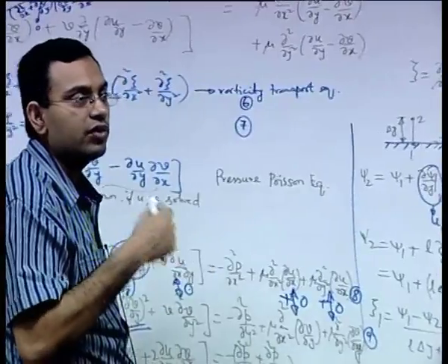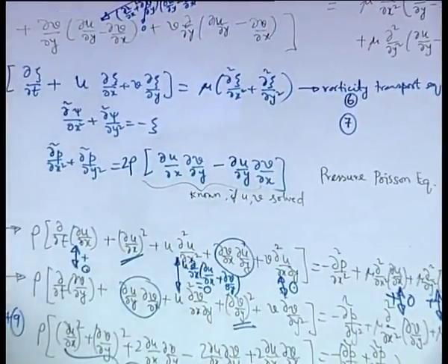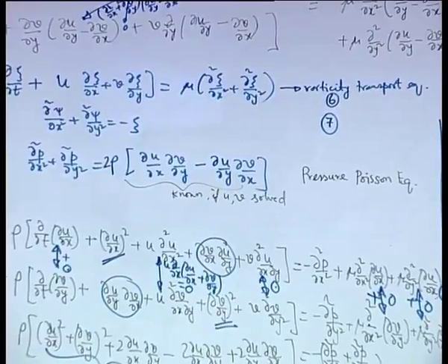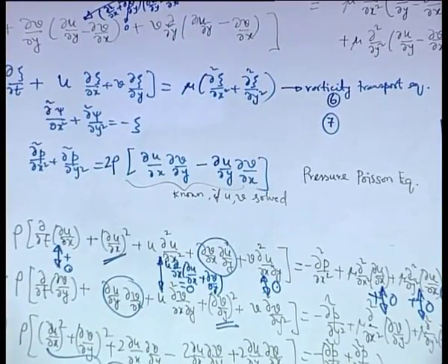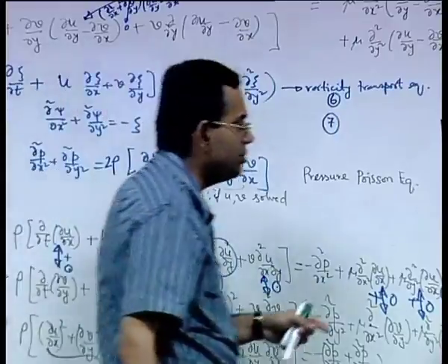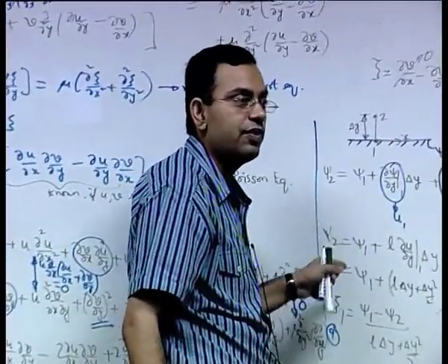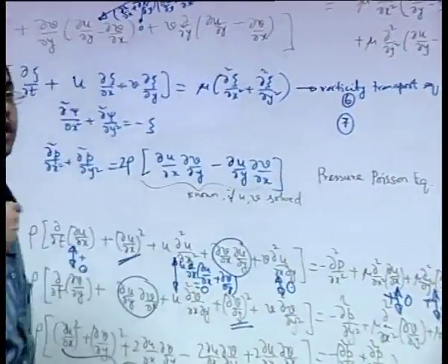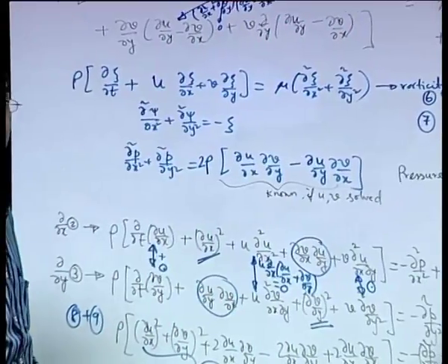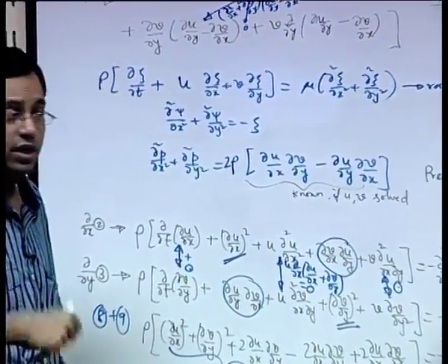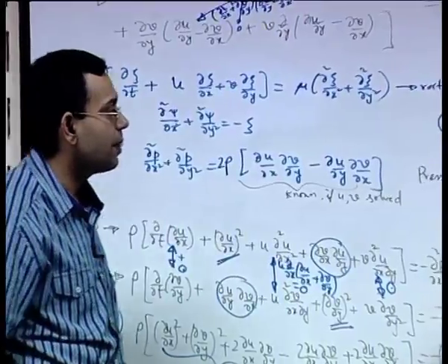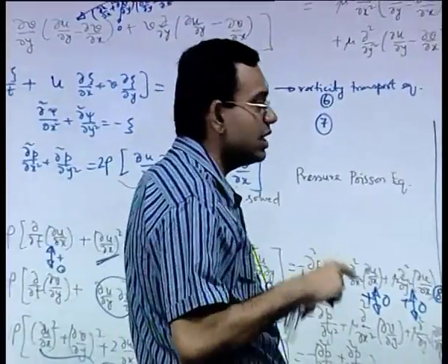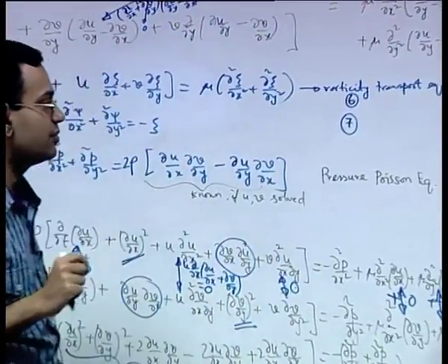So, the vorticity boundary condition is not something which is coming from basic physical arguments, we are writing it from the Taylor series expansion of the stream function. So, it is a mathematically derived quantity, but not a fundamental input physical parameter, that is one, but still it would have been okay. The more general problem is something like this.